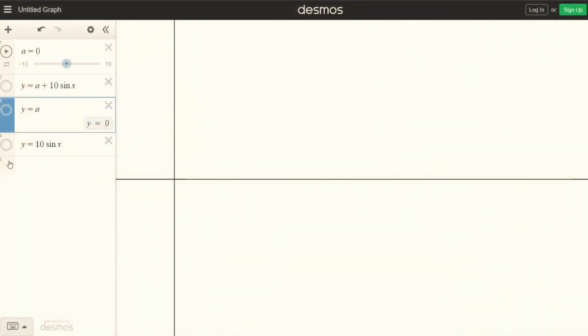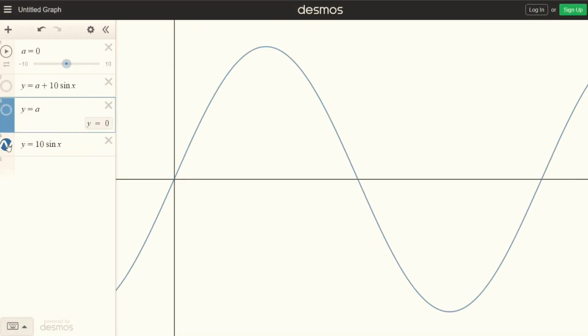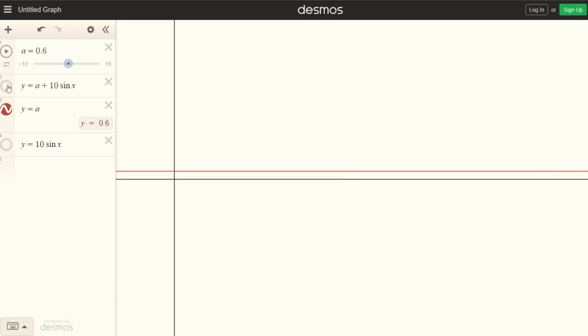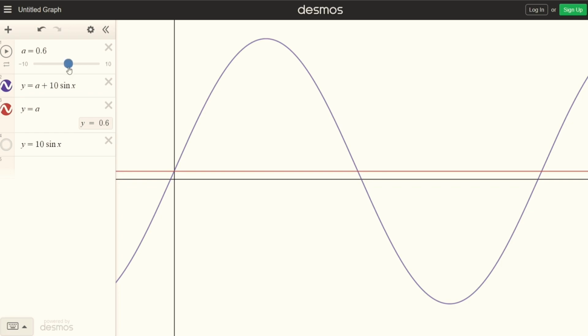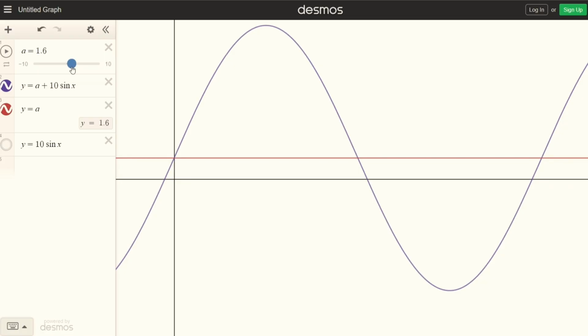However, going back to our modern electronic loads, the injected DC causes the AC waveform to become polluted, effectively. We can illustrate this using this lovely graphing software from Desmos. Here we have a healthy AC waveform, and here we can see what a DC waveform looks like. You see there it's just a straight, flat line. Now, the problem occurs when we combine the two by leaking DC back into the AC supply. Because as the DC combines with this AC waveform, you can see it lifts the whole AC waveform up the y-axis.